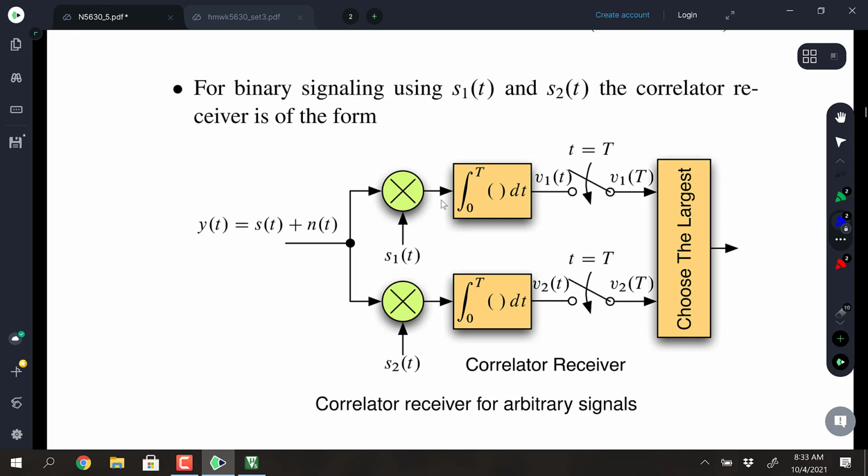In radar systems, they're designed with a different requirement, and this is part of statistical decision theory. Radar systems might be designed to be what's called CFAR, which stands for constant false alarm rate, which means you want the maximum probability of detection, but you want to ensure that the probability of a false alarm, in other words, declaring a target present when there isn't one, holds to a very small probability, like say 10 to the minus 6th or something,